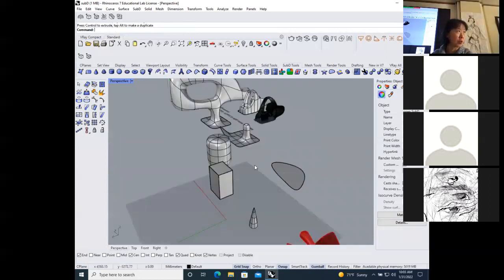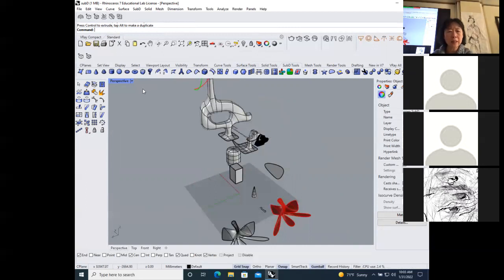I have a tutorial. You can watch the tutorial. By the way, those tools, they look very familiar to you, right? Agree? And by the way, the trick about the SubD is you start from a very simple surface. You do not start with, for example, this, there's a create a 3 SubD surface. So the count is 2 and 2 and 2. None is actually good. Let's say if you set the count as 20, that means 20 by 20 by 20. So each surface has 20, X and Y and Z.